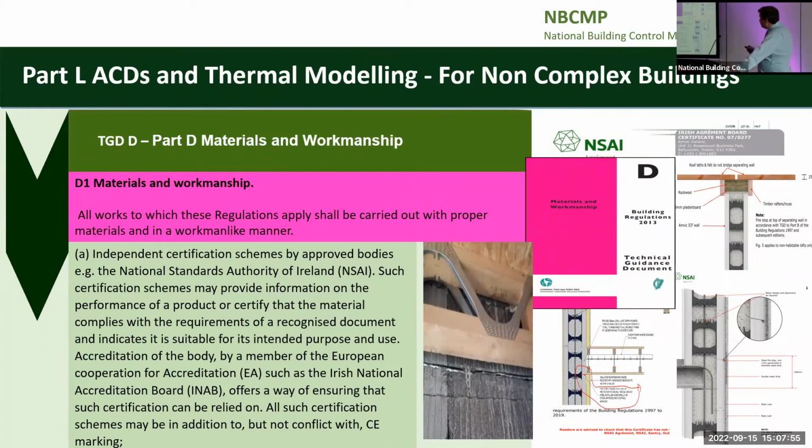And the other thing too is these junctions need to be thermal modeled, you know? So the concrete floor one versus the timber could be totally different because you're breaking the insulation here. That's a straight wall, technically.